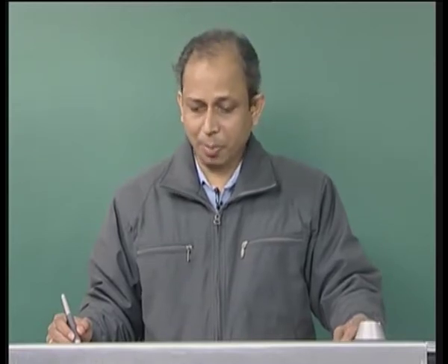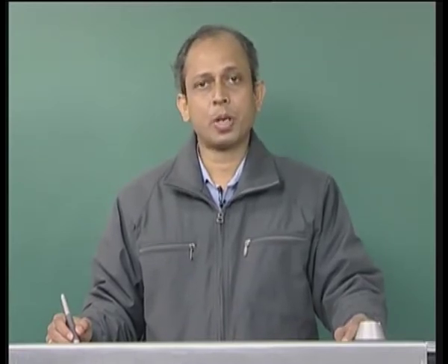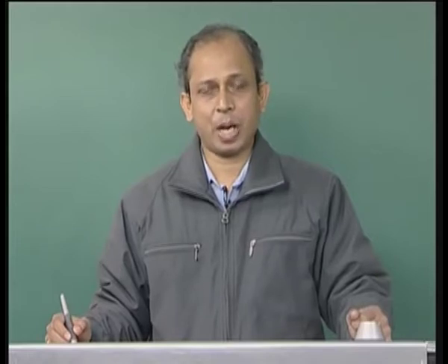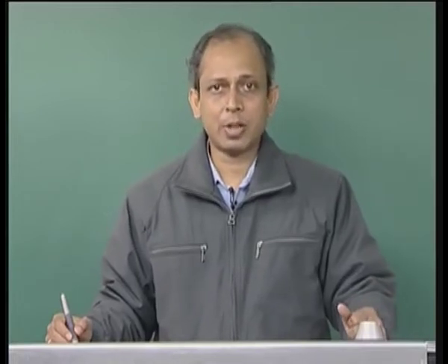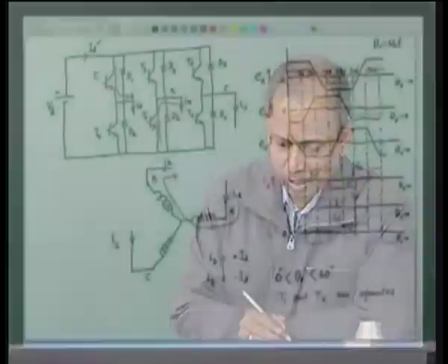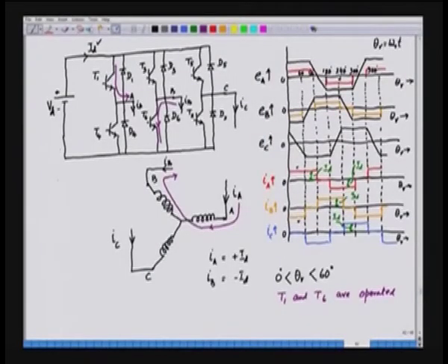In this case, we have a trapezoidally excited motor where the waveforms are trapezoidal, and the current in this case are quasi rectangular in nature, and the current exists when the voltage is positive. Now, let us try to calculate the power in such a drive. Now, here if you see the power in this case, P is because of the currents in all three phases.